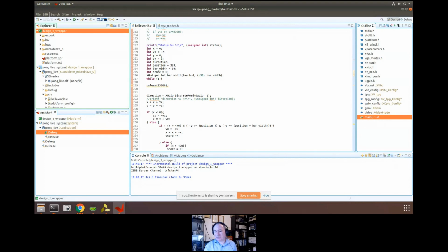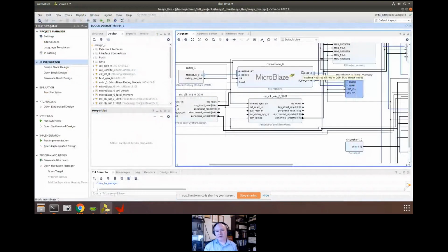So, just to come back to your question, Ken. Vivado is where we captured the design, in lab 1. It's where we created the block diagram, where we put the MicroBlaze in there and so on, and that's all working in VHDL, in RTL, and in the outputs from the high-level synthesis tool. What we export from Vivado is a hardware definition and a bit file for the FPGA, and we bring that into Vitis, and it's in Vitis where we write the software, the C, the C++.